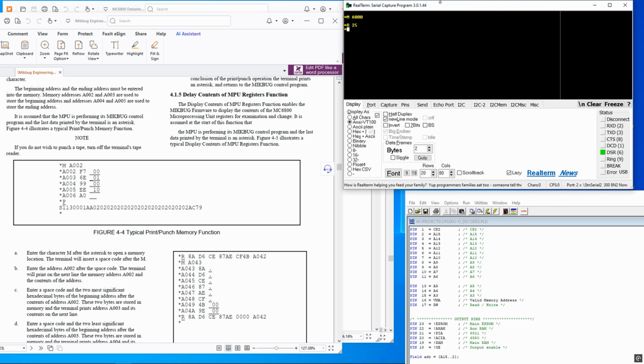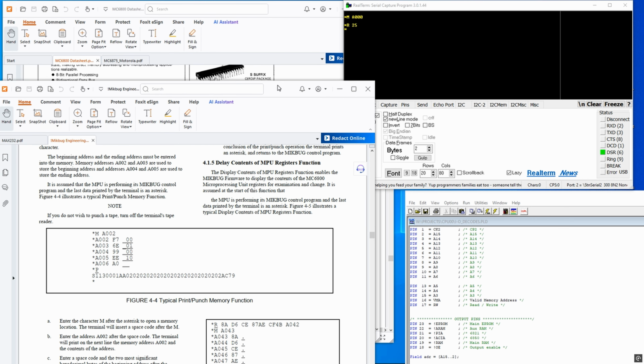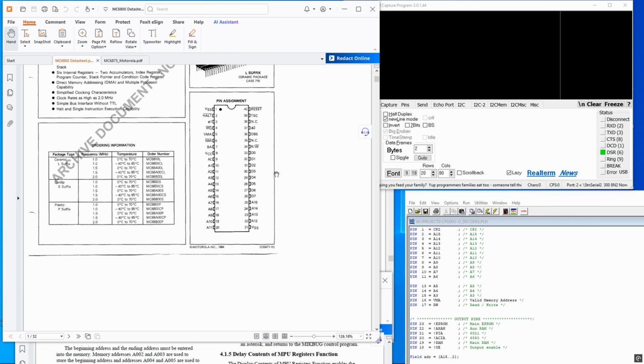Going over all the pinouts where I'd missed the pull-ups, I checked all the other pins, and there is a line on the processor called VMA, Valid Memory Address, and that is actually supposed to be used as part of the memory decoding.